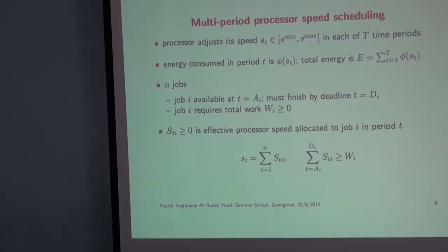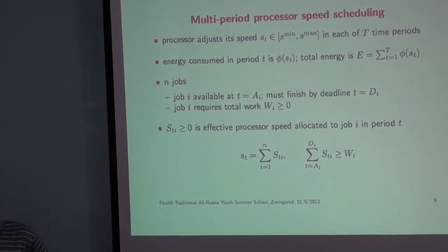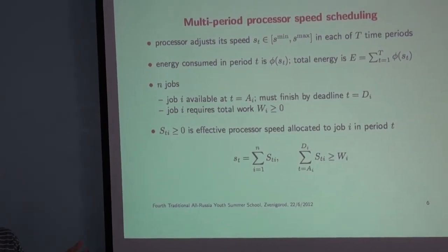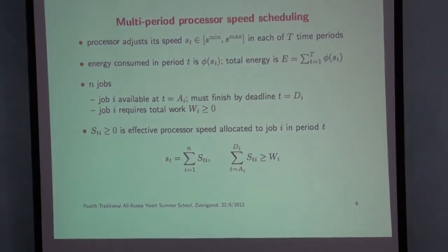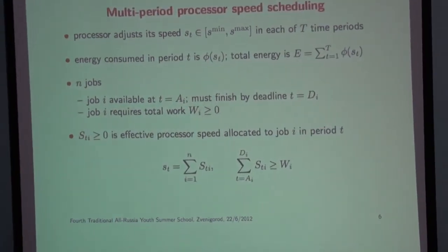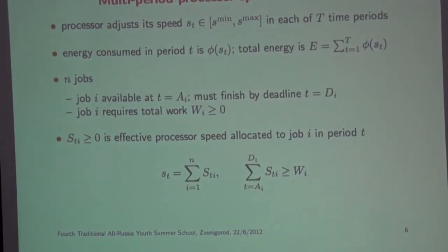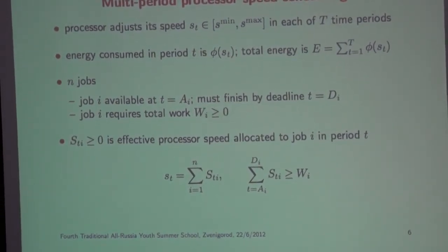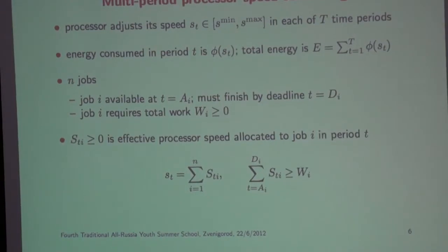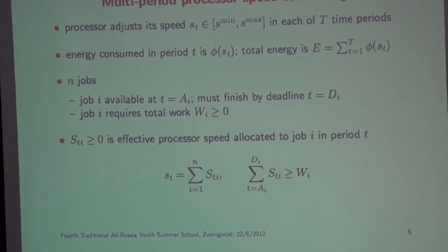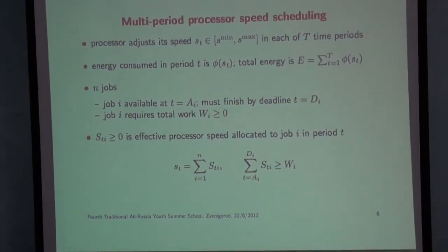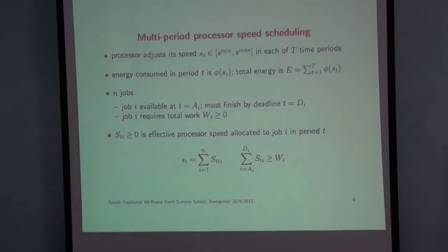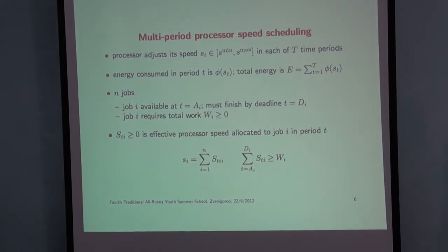This thing is always convex, in fact, because the marginal cost, if you run at higher clock speeds, is higher, right? And in fact, for most modern processors, this thing is very close to just a square. It's not for a simple reason. It's like 20 different reasons put together, and somehow when you plot this energy versus speed for a modern processor, it looks like a square.